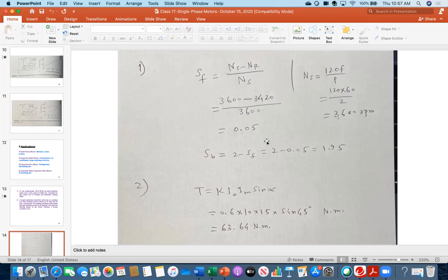That is the reason that in any electric machine book, the single-phase induction motor chapter is always placed later than the three-phase. I noticed the same thing when I was an undergrad student like you, and I always wondered why. Many new books by many authors still place it later because it is somewhat complicated in theory. Because of the forward field, backward field, you need the auxiliary winding, and capacitors come in. But when we discussed the three-phase induction motor, we did not face those problems, because the three-phase created a rotating magnetic field, so there was no lack of magnetic field speed. That is the difference.